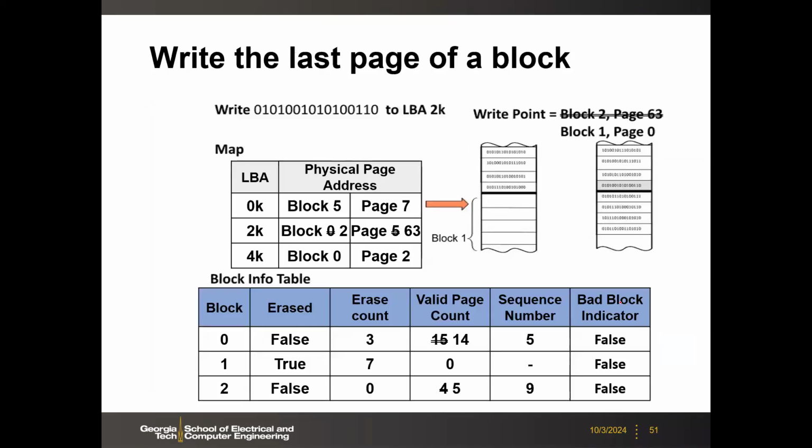The reason is that with NAND flash, as I said, when you write or read, it's page by page, one row by one row. But when you erase, it's the entire block. Once you erase, the entire block's data becomes one. So the goal of writing, or programming, the data is to flip some ones to zero. Initially all of them are one. Now you want to write new data after you take the picture, you save the picture image, and then some of them become zero.